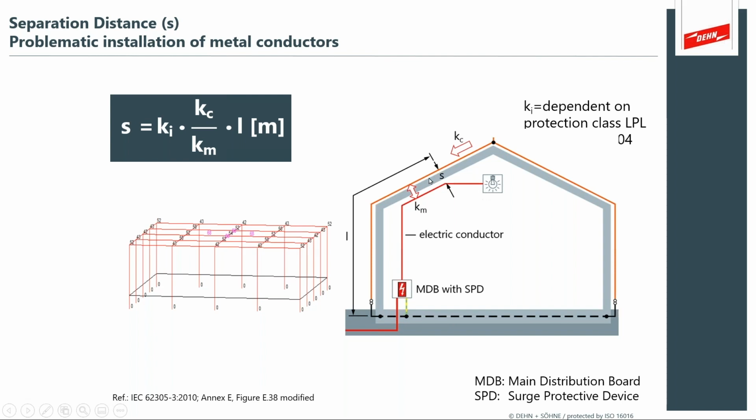And so the standards, the IEC and the NFPA methods, are very similar in how they calculate this distance we're calling S. In the NFPA standards, they use D for bonding distance, but it essentially turns out that those distances are the same for an LPL3 and an NFPA method. So it's nice to see the standards are harmonized. This aspect of a lightning protection system is very well globally agreed upon.